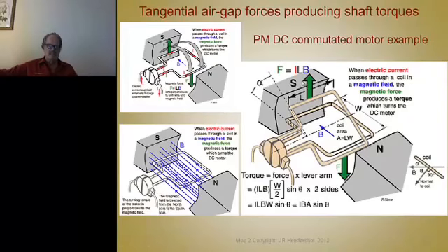But the other thing is, with this big a gap, this B field here is going to be awful weak, so there's got to be something else here. There's got to be some iron inside of that, and if you create a big force, 100 Newton meters or something like that on a wire, well, it's going to bend. You've got to have something to support it.